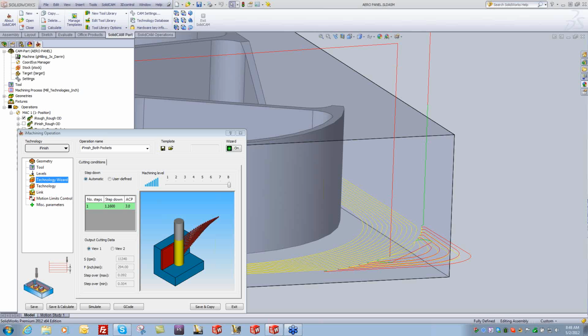So yes, you can. Like let's say you had blades and you're cutting a turbine. You said will, but if you're cutting an actual, what am I thinking of, a fan blade or something like that, you can absolutely rough this out in 3-axis, not simultaneous, but in actual positioning.